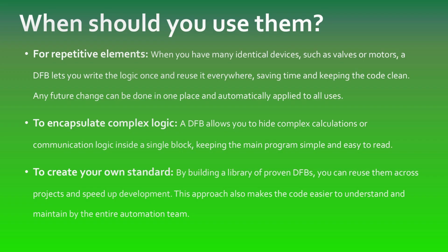Easy, fast, and error-free maintenance. To encapsulate complex logic, if you have a difficult mathematical calculation or a complex communication protocol, put it inside a DFB. That way, in your main program, you will only see a clean block, hiding the internal mess and complexity.